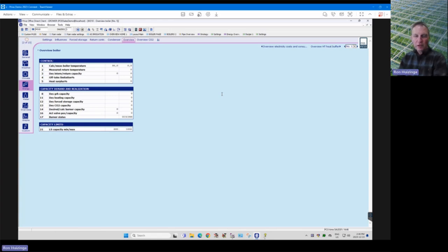Yeah, so basically, the CO2 fans, they usually put the piping underground. Sometimes it's above ground, but most of the time it's underground, and then it's got all the tubes. Like for vegetables, basically there's a plastic tube that's around 2 inches in diameter, clear plastic tube, with a bunch of holes in it that they run under the gutters or in the crop, and that spreads the CO2 out throughout the greenhouse.